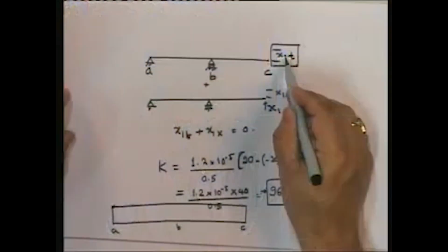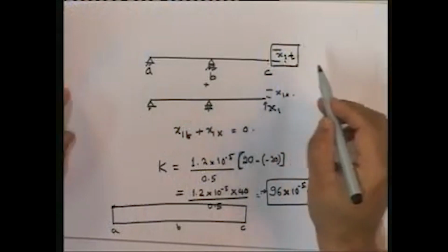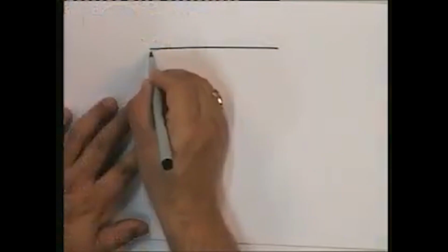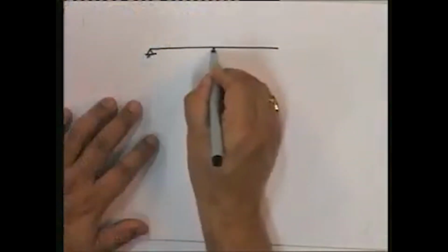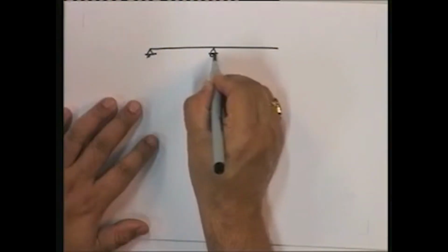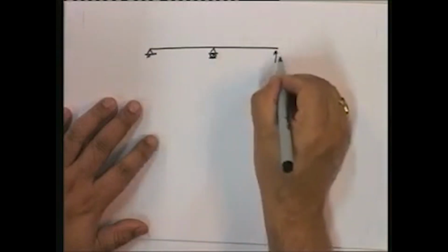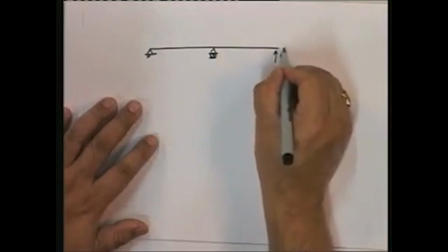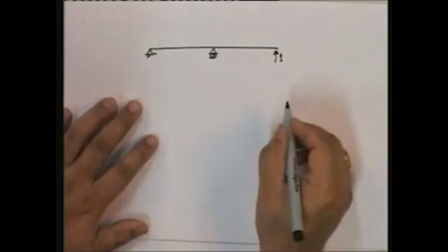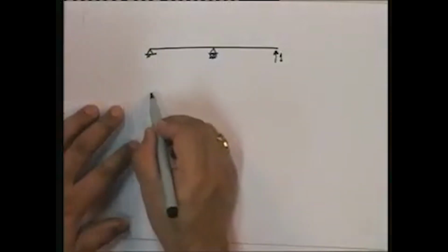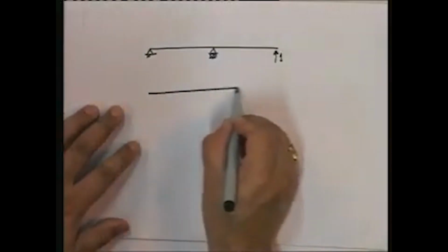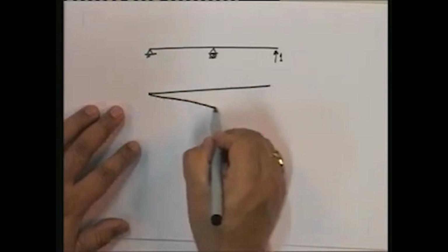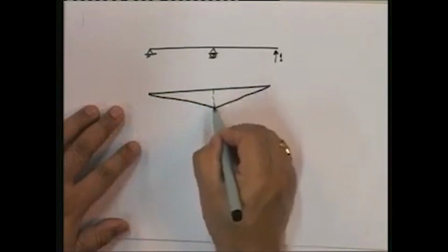So, does that give an effect? I need to find out what does that lead to in terms of this. So, what do I do? Well, again, using the principle of virtual work, which is really to find out a displacement, I give a unit virtual force corresponding to the displacement, and I find out the internal forces. If I look at the internal forces, what do I get?